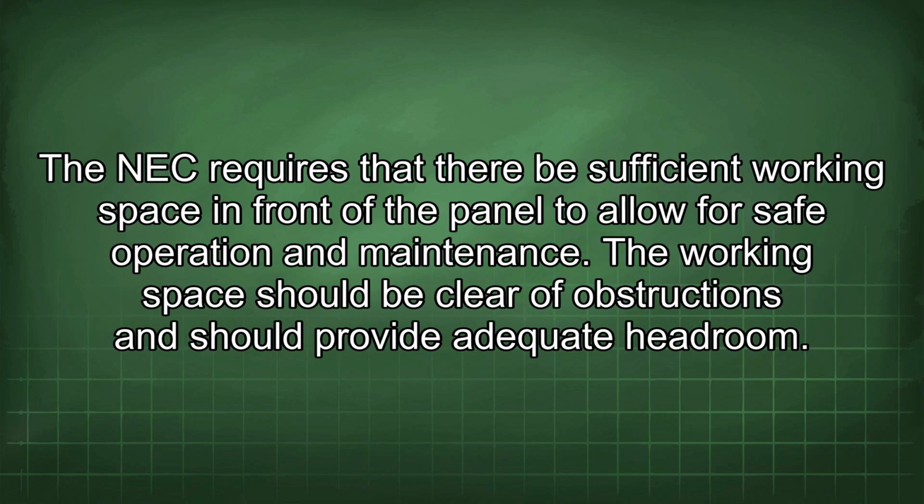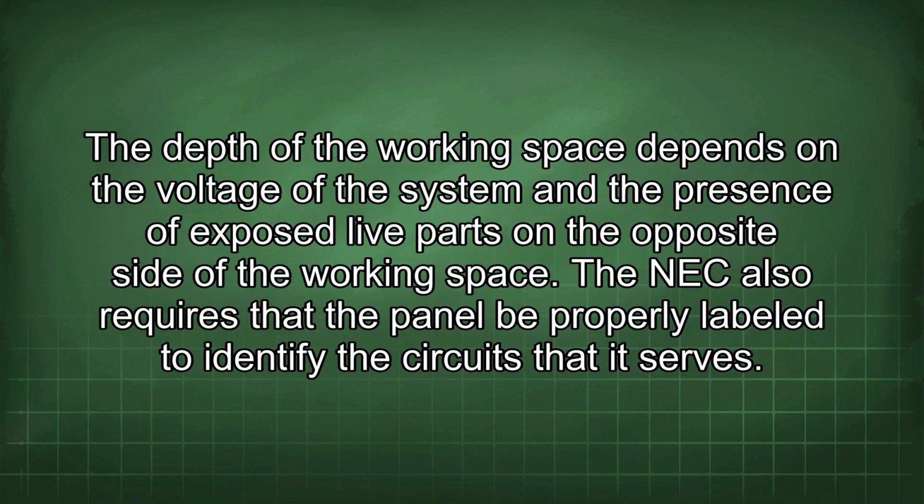The NEC requires that there be sufficient working space in front of the panel to allow for safe operation and maintenance. The working space should be clear of obstructions and should provide adequate headroom. The depth of the working space depends on the voltage of the system and the presence of exposed live parts on the opposite side of the working space.